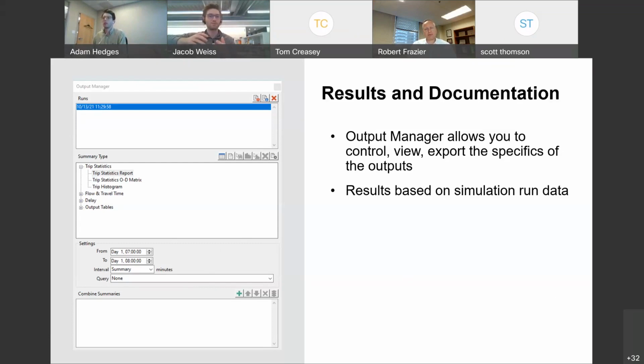It might prompt you to create a super link, which is more or less just chaining a number of links together so that you're able to collect queuing data that's maybe a little bit longer than an intersection from one node to another node. So there are some built-in checks as you are going into a simulation that you do want to clean up some of those warning messages if you are exporting something like queuing at an intersection, or even some intersection level of service and delays.